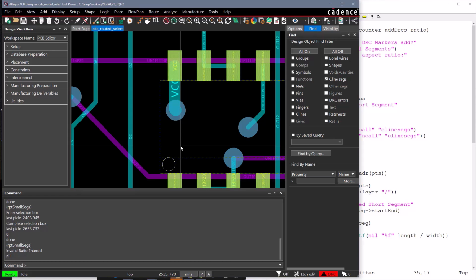In summary, the PCB Editor Skill API includes a set of high-level user interface functions that allow you to programmatically solicit information from the user. There are simple confirmer windows, yes/no dialog boxes, a file browser, and a multiple choice dialog, to name a few of the most commonly used UI functions.